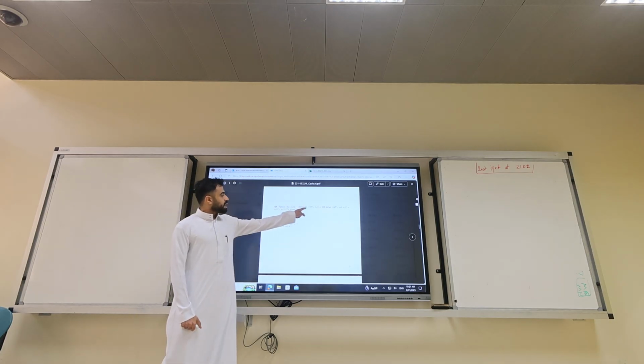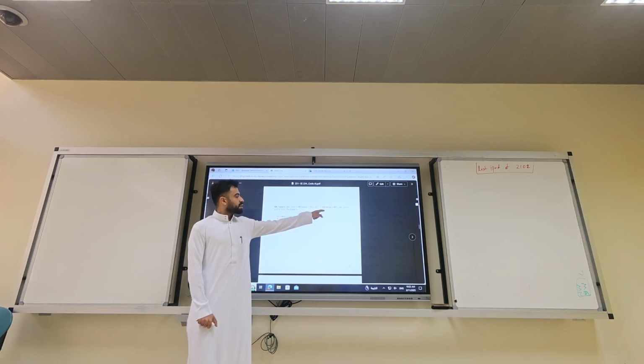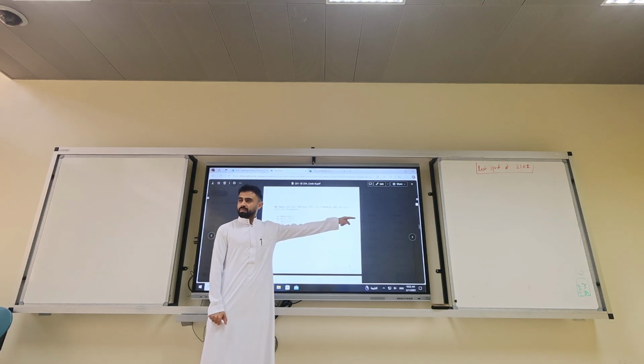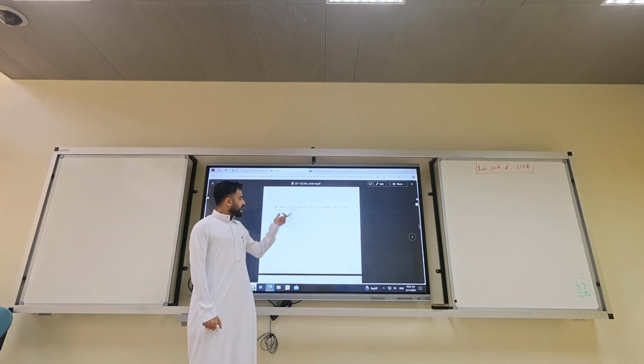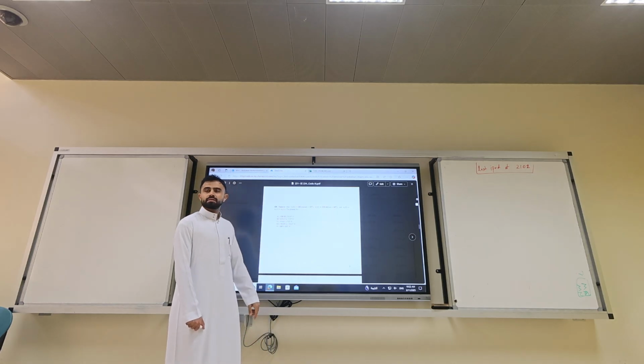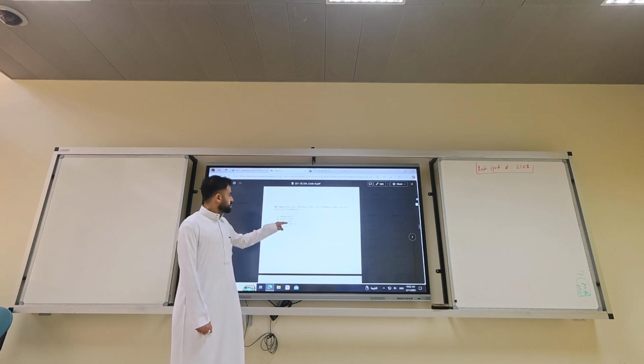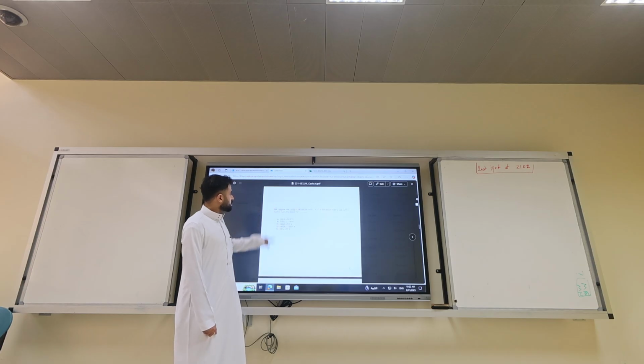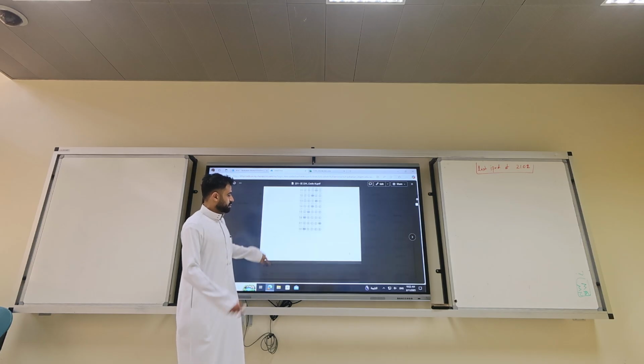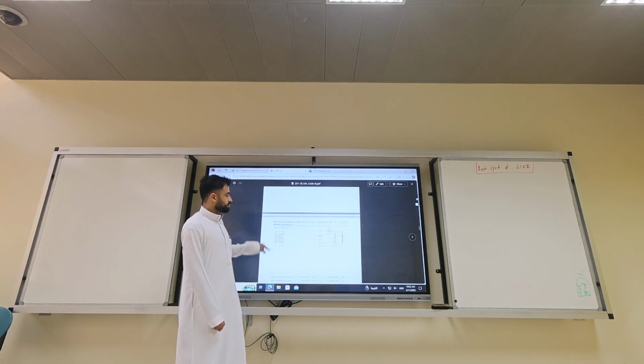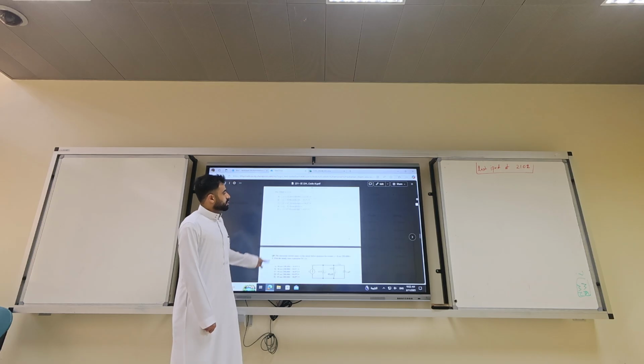Well, it is 100 angle 45 plus 100 angle 60 minus 30, which is minus 30. Add them together, what's VS? It is 158, angle 7.5. Plus or minus? Plus. So it's C, so 6C, it's C. 6C, you got it right. Yes. Okay?